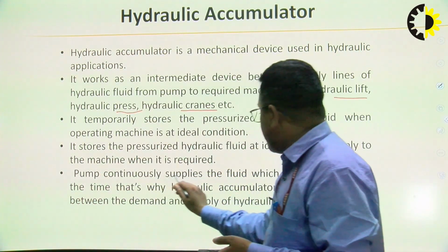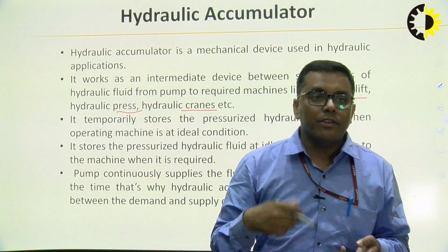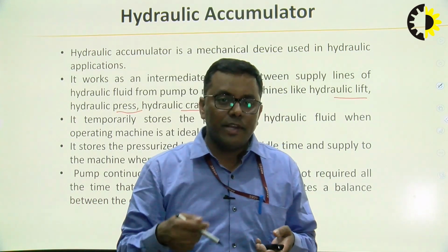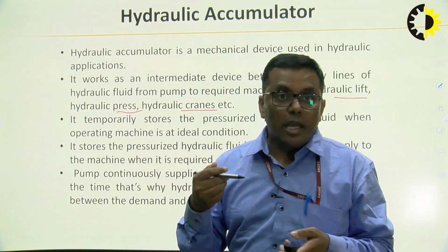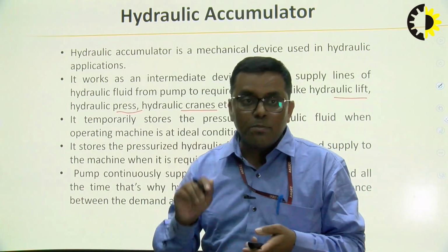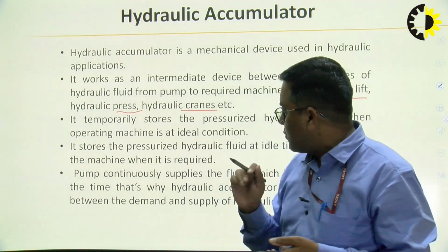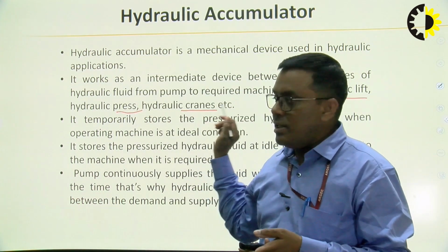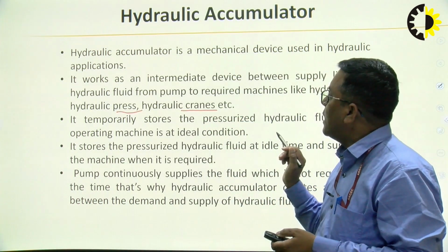The pump, either a reciprocating pump or a centrifugal pump, is continuously delivering high pressure fluid. If that much amount of fluid, that much energy, is not required for the certain application, then that energy is getting stored. So that is what the hydraulic accumulator does.